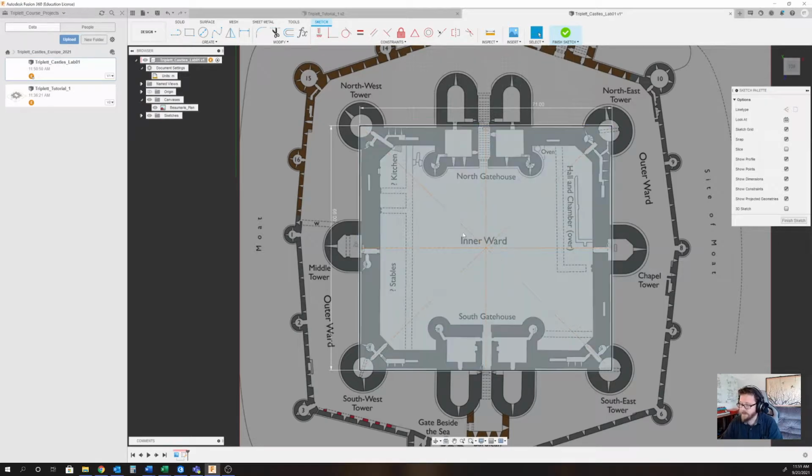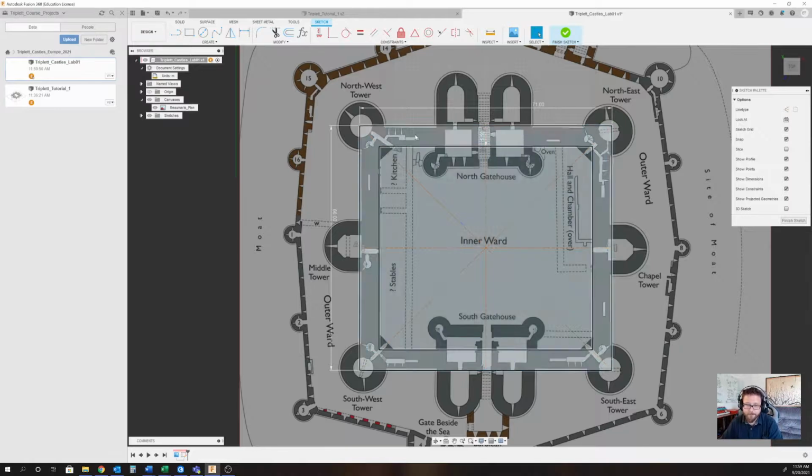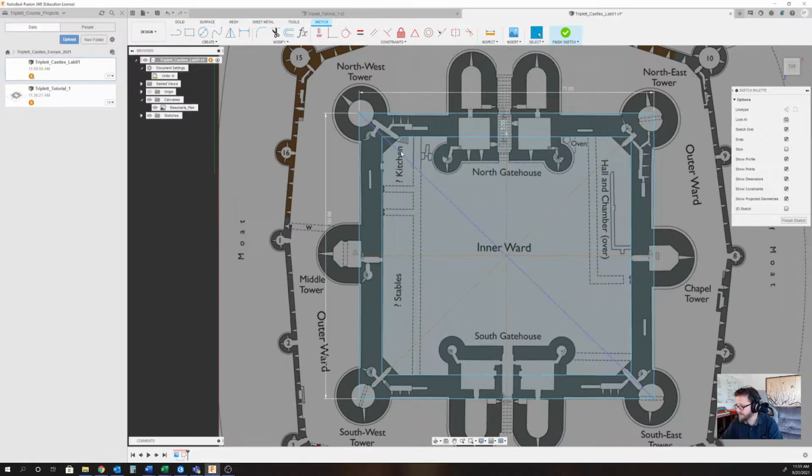So let's create some thickness for these walls. That's pretty easy. Another thing you can do is if something is contiguous, like all of these lines, you can simply double click them once and it'll select all of them. And then we're going to hit the offset key, which is up here under modify. And I'm going to start pulling this in. And I think, let's say 5.5 meters for that. Okay. So that's going to be the thickness of our walls, 5.5 meters. Okay, that's useful for us.